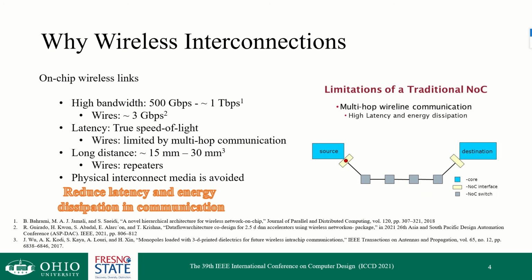for DNN. We demonstrate a typical wireline communication paradigm in the red figure. Messages have to propagate through multiple intermediate switches to get to the destination, incurring high latency and energy dissipation. The situation gets worse when the accelerator design scales up. Wireless interconnections inherently support distance-independent one-hop communication, which alleviates this problem very well. Prior works have reviewed the potential of on-chip wireless interconnections to provide high communication bandwidth, no excess latencies, and high power efficiency, as I cited at the bottom.